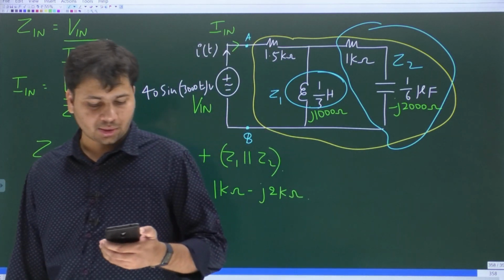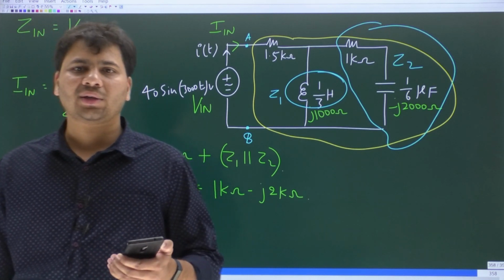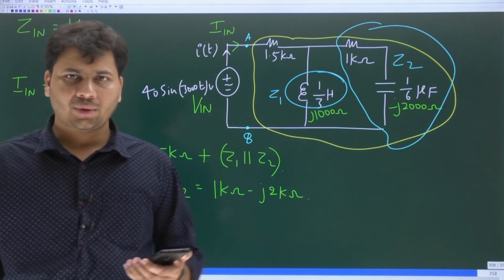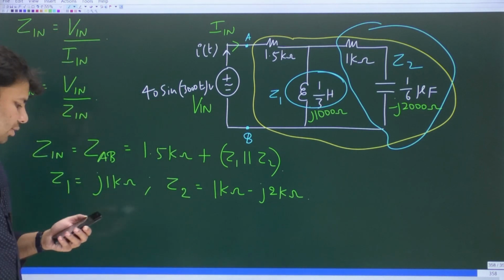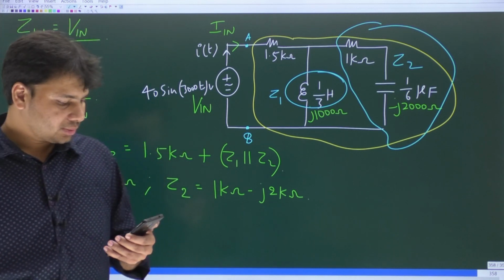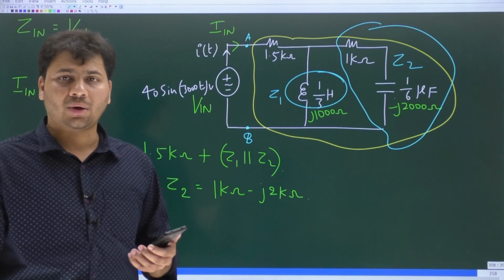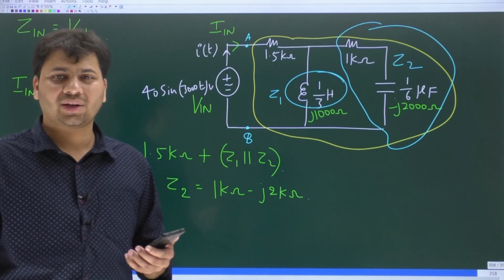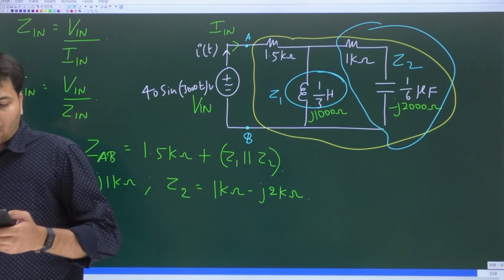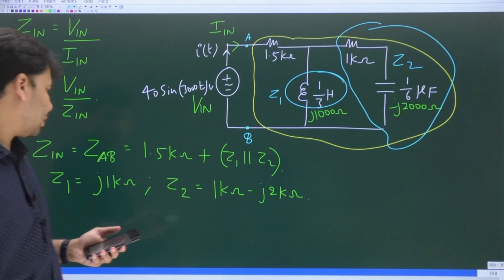Okay, Dineshwaran is saying 2.25 at an angle approximately 36 degrees. Units, is it not kilo ohms? It should be kilo ohms because here everything is in kilo ohms. Even the resulting input impedance would be in kilo ohms. So Zn, I believe this is correct. 2.25 kilo ohms at an angle 36 degrees. Let's call it 36 degrees, okay? I hope others are also getting the same thing for the input impedance, okay?